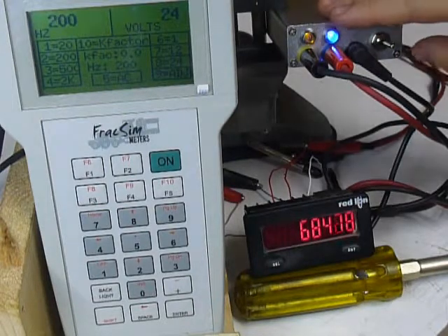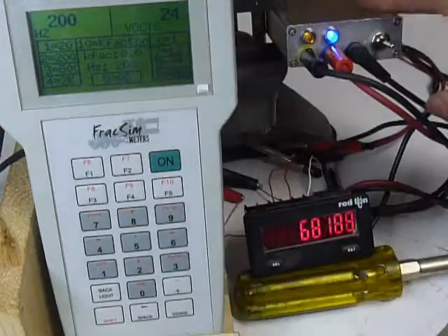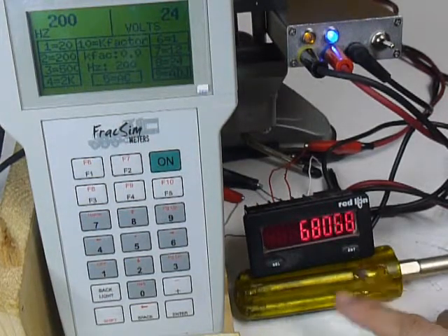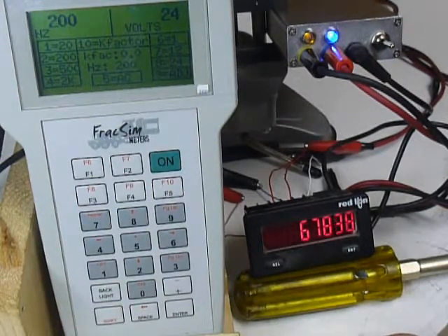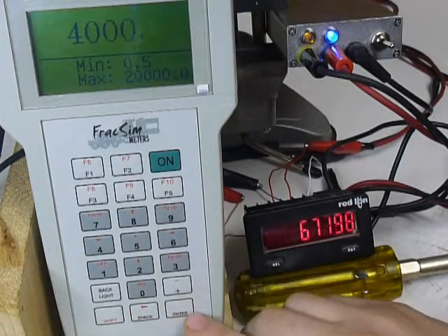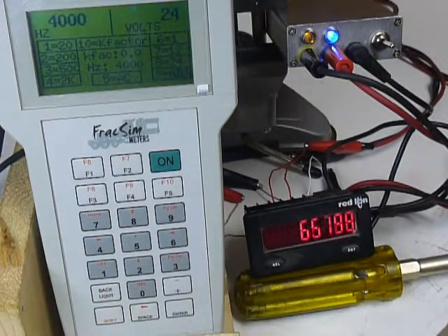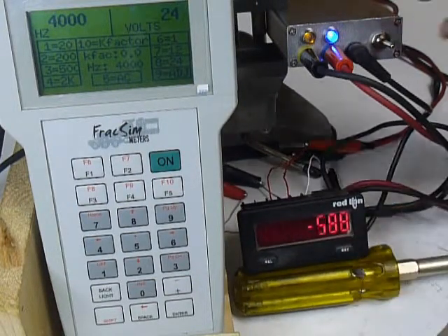Now the way this thing works, it actually takes the frequency and it divides whatever is going out to it by 4 for this output. So 200 hertz would actually be an output of 50 hertz. So if you wanted 1,000 hertz, you'd have to put this at 4,000 hertz. So 4,000, and now we'd actually be doing 1,000 hertz. There would be no totalizer functionality, but you'd still be able to test encoders and make sure they're going backwards and forwards correctly.